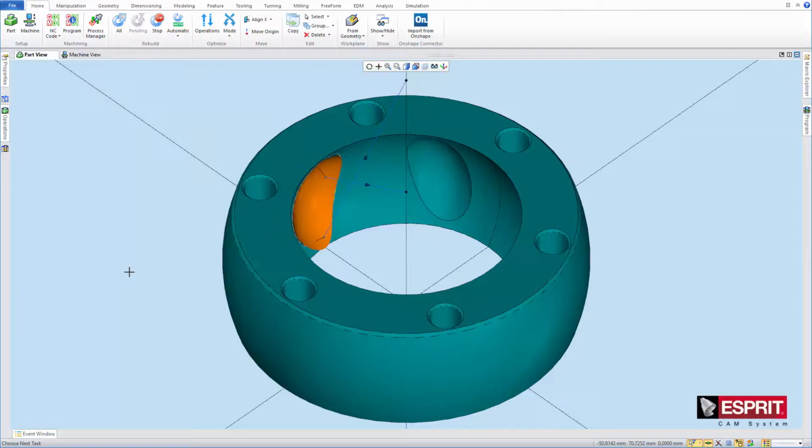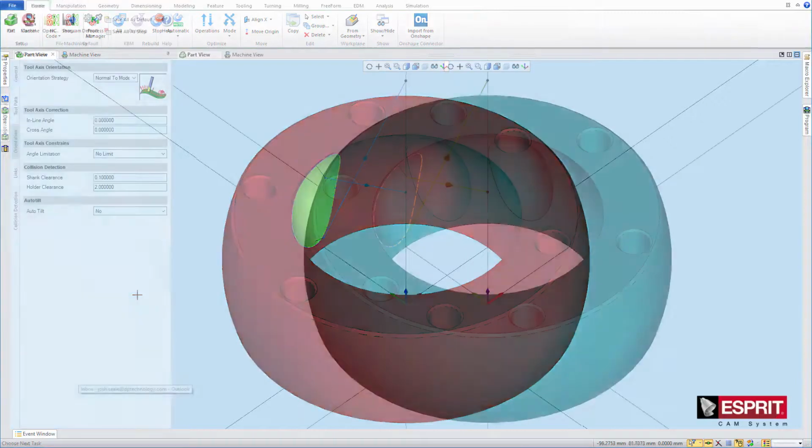A smashed surface was created from this concave face. Normal segments were then created near the top and bottom of this surface, and then chains were constructed between the ends of these segments and the z-axis. A freeform feature was created, designating the concave face as part and the rest of the model as check, and a composite operation is applied to the feature.